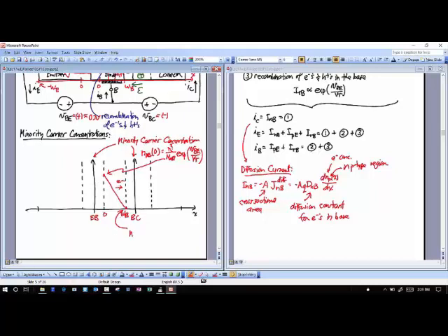At this point right here, at W_B, I'm going to write an equation for n_pB at W_B. This is also going to be equal to whatever the background concentration of electrons is, which is that same n_i squared over N_AB, where N_AB is the acceptor concentration of the base. Also times e to the voltage across that junction. The voltage across that junction is V_BC over V_T, but that is a negative quantity because V_BC is negative, right? I take e to the negative power, and a rather big negative power maybe. What does that equal? Nearly 0. Very small. So that's why graphically I've drawn it like this.